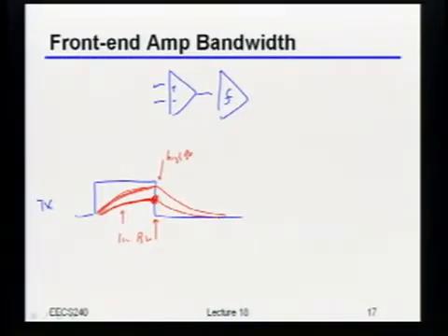Yeah, the SNR is worse. I have a smaller input signal. Because I didn't settle all the way, I'm getting a smaller voltage difference fed into my comparator. So in order to decide what bandwidth you should be using, it's really going to be set by how much loss of signal